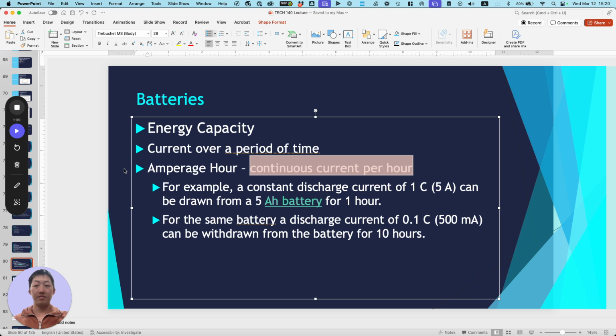Let's see. Why you choose one over the other? Not exactly sure. It's just, I don't know, one company wants to use one over the other. But the size does matter based off the cable size. So when you have a thicker cable, it can handle more current. So that's why you're going to see it proportionally. You're going to see an XT60 on a battery that's bigger and it can handle more current than this one. This battery is considered lower. That's why they put an XT30 on it.